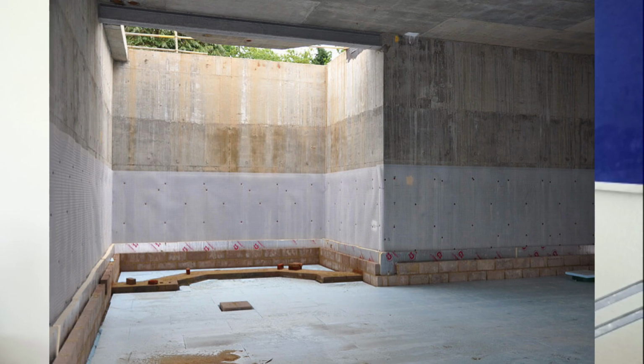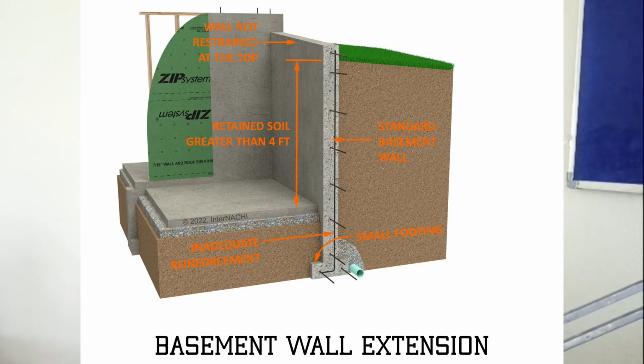Your basement is coming below ground level, so in most cases in the rainy season water may come. To prevent water from coming inside, you need to apply a waterproofing coat to that retaining wall, so that the water coming from the earth won't get inside.